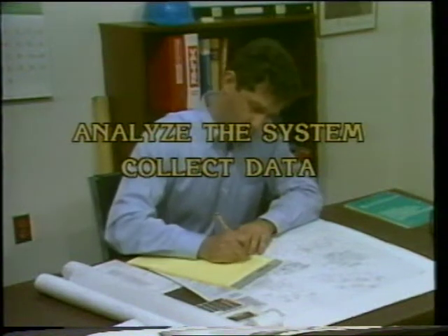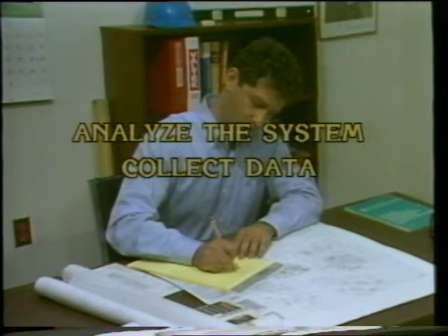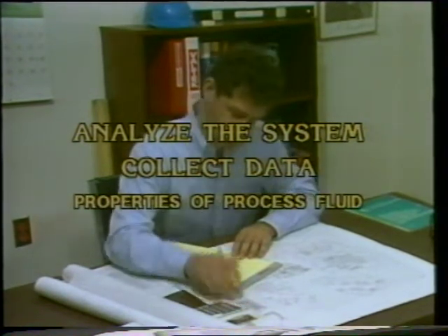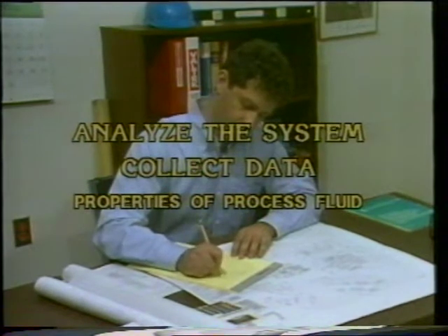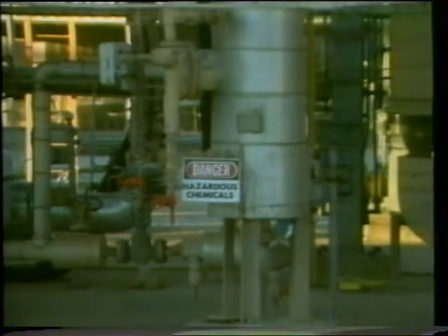required fail-safe action of the valve. But obtaining other information may require some research. You'll need information regarding the properties of the process fluid as it will exist at the valve inlet. This includes chemical properties of the fluid, which may influence final valve selection.